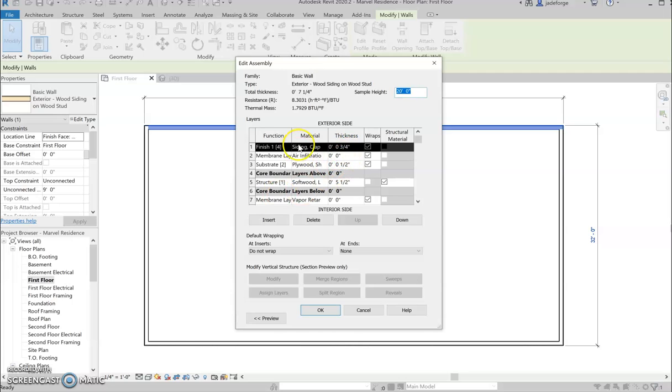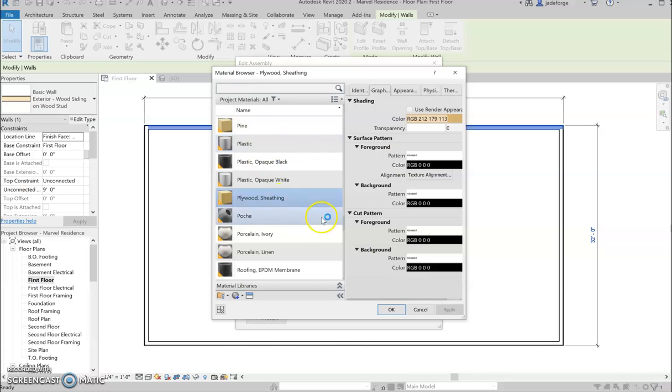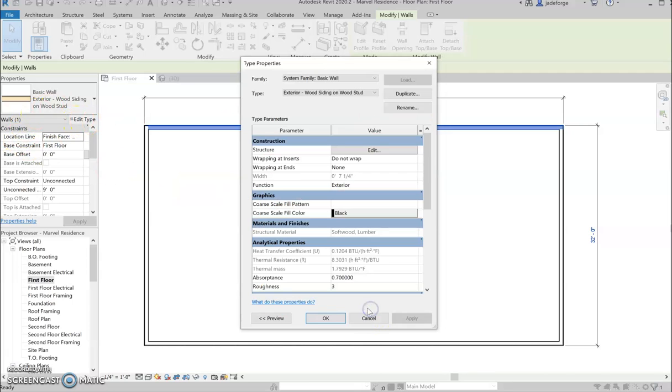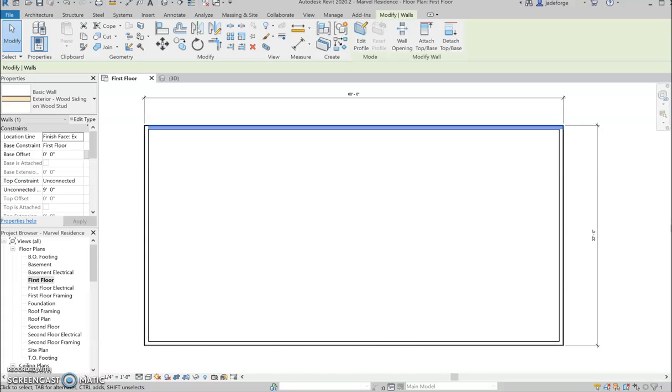It shows you the thicknesses, it shows you the materials. You can even click on the materials and it shows you these 3 little dots right here. We could go to that and it goes to another box and other options, a ton of different materials, again, built into this Revit program that we could choose from, and we can manipulate what the template is and save it within this project. It won't save it for future projects, but it'll save it for this project particularly. So you can go to the edit type and we can edit different things within the wall structure.